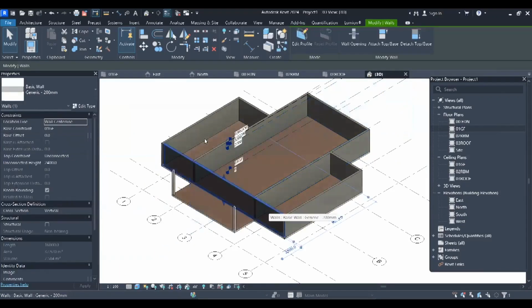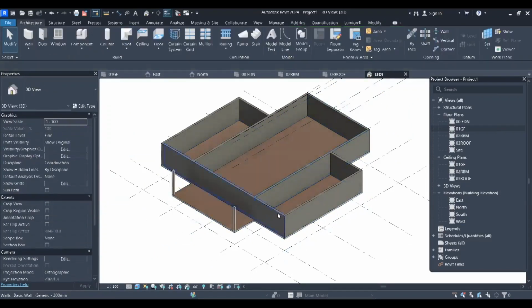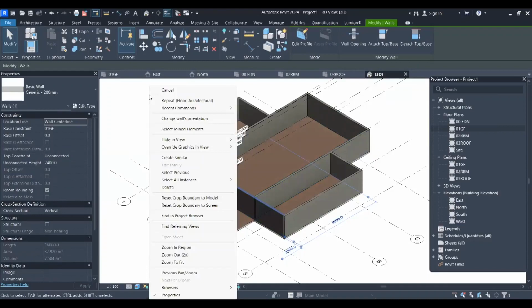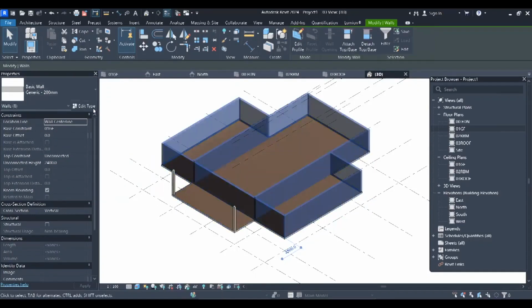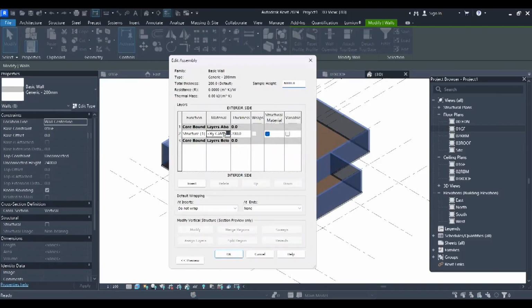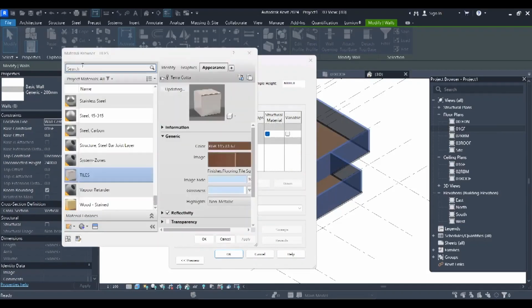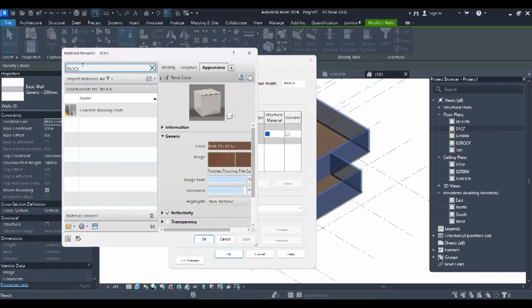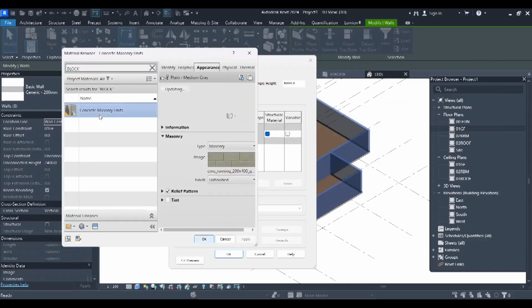So if I want to change my wall, I said right click, then select all instances visible in view. Then I don't need to go far. When I come here to edit material, for category, as I have shown, I want to use blocks. If you want more decorative things, you go through the same procedure. You create a new material, name it how you want, then you come again to browse, and they will come. But let me use blocks.